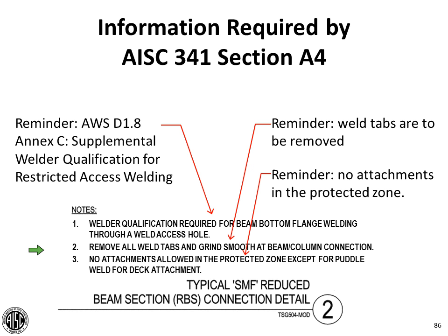And then in this detail, there were some additional reminders, I guess, related to the seismic requirements. In AWS D1.8, there is a requirement for welders that are making the weld. Generally, it's the weld of the bottom flange of the frame beam to the column flange. Because they have to weld through the weld access hole and then stop and then start again on the other side, they have a restricted access in that area. And so there's a requirement that these welders pass a specific test in order to be able to perform those welds.